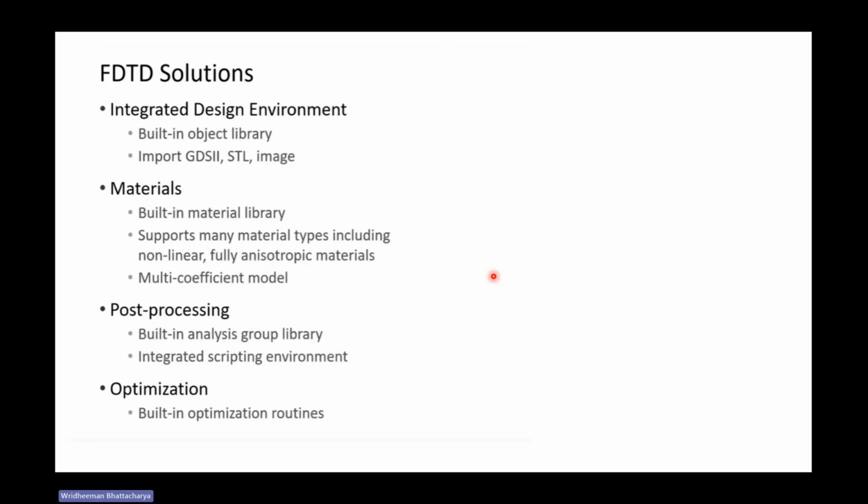This FDTD solution offers an essential and interesting thing: if we have a SEM image, a litho image, or an AFM image of a nanostructure, like suppose we have fabricated it first and did the study, we could import that same image into our numerical FDTD solver and create the structure.